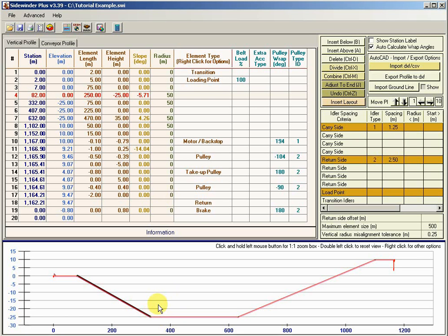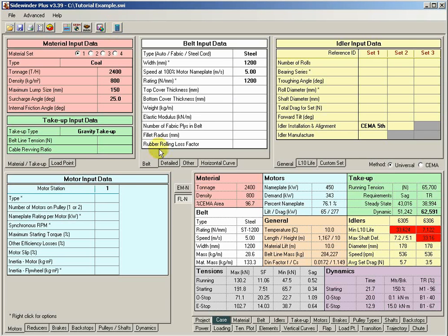Obviously, if you've got a given tension, be it 10 kilonewtons, the belt's going to lift off. You're going to have a more stringent requirement if your belt mass is reduced. So that worn belt mass case is typically your governing design condition. We'll talk about that more in the advanced calculations. But for now, we've simply entered 50 for each of our radiuses. I'm going to go ahead and hit the Run button.